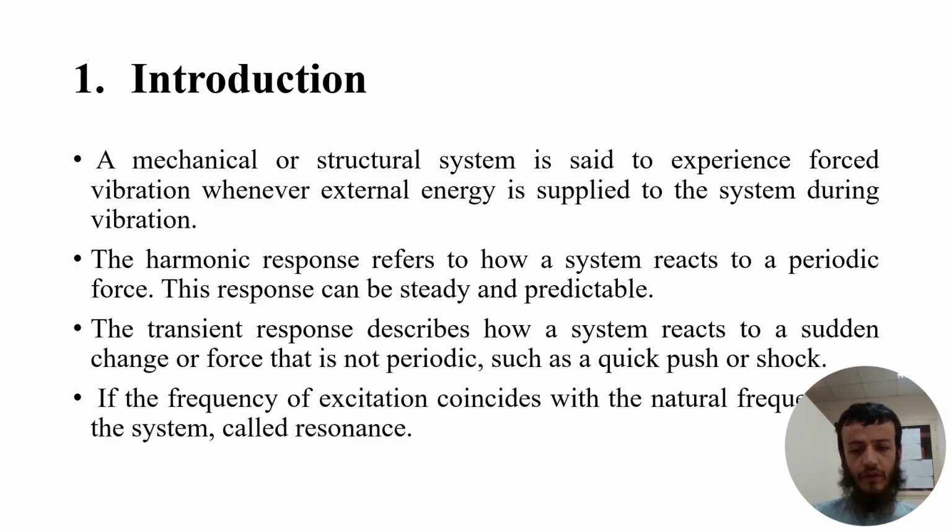If the frequency of excitation matches the natural frequency of the system, at that time we have resonance that leads to a very high response, and resonance is to be avoided in mechanical vibration systems because of the failure.